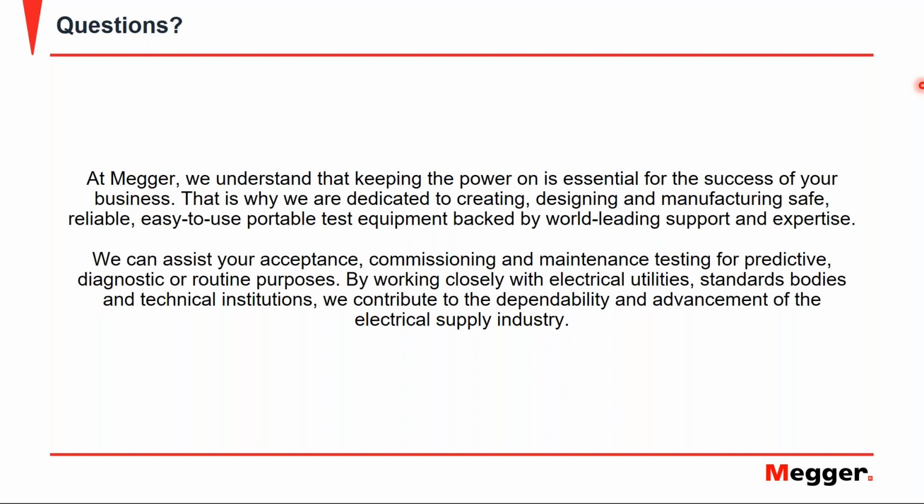Good. So if I understand the question correctly, then what is meant here is that a utility is performing Tangens delta diagnostics, and based on the outcome of the Tangens delta diagnostics, they want to plan a PD diagnosis. Well, like Jason already mentioned, these are two different measurement methods or measurement types. The Tangens delta is a global one, looking for the aging of the insulation, so normally for XLPE cables it should be the water trees, or for paper cables, moisture content. And